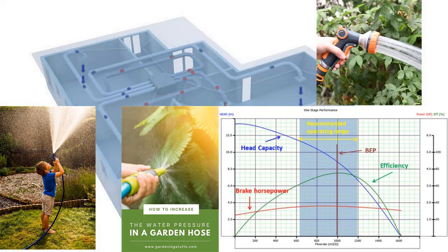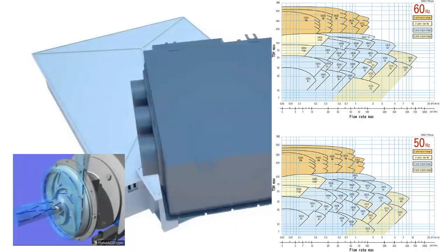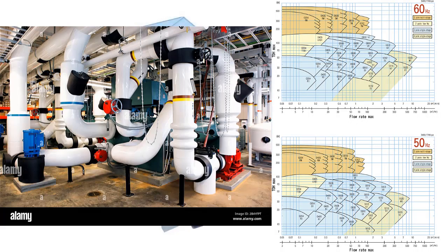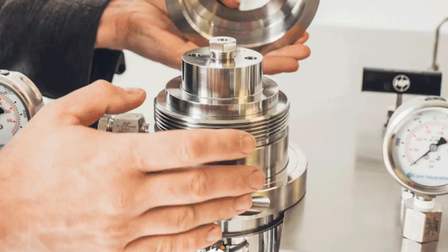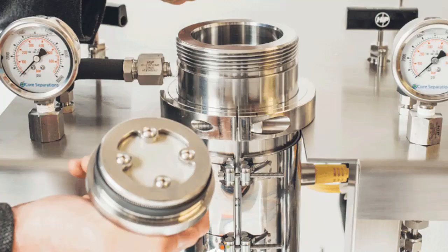The velocity, or speed, of the water coming out will increase as you are forcing the water through a smaller area, but let's just stick to flow and pressure for now. So if you have a restriction in your pipework, such as a water strainer blockage, the pressure upstream of the blockage will show an increase in pressure, but the flow rate will be reduced. Let me explain this from the start.